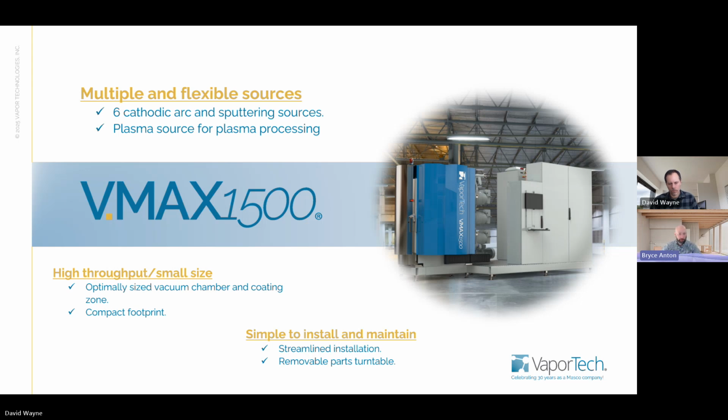We're using turbomolecular pumps on this system. It's also equipped with an independent plasma source. There is a plasma source that we use for gas phase etching, as well as for the PECVD of the DLC. And it can also be used for metal nitriding, which is another way to enhance the toughness and the durability of the substrate prior to building up the hard coating.